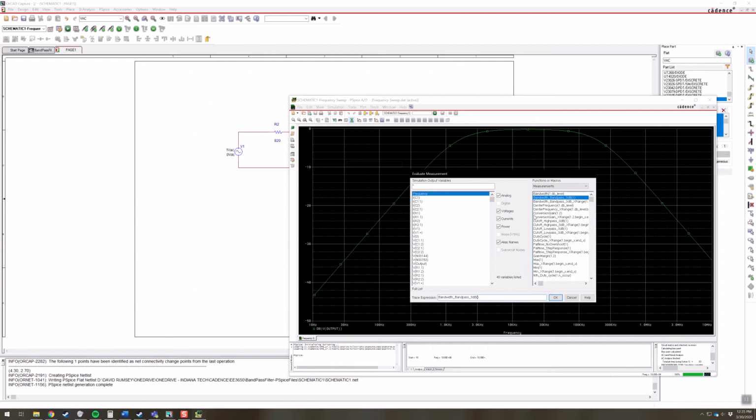So this is saying the bandwidth using minus 3 dB level. Bandwidth, if you want to give it a particular decibel level, that's when you want to do that. And that might be, for instance, if you're wondering what the bandwidth is at -6 dB, or maybe you're getting gain, and so you want the bandwidth at 17 dB or something of that nature.